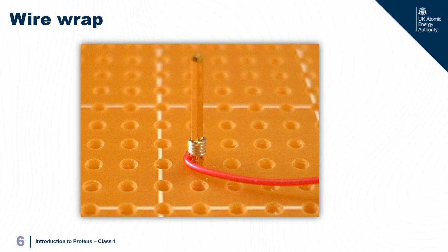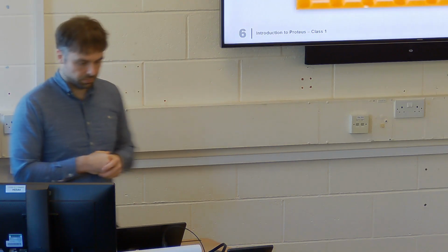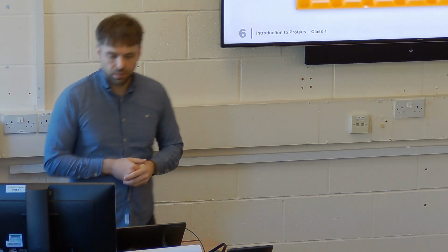So moving on from that, we developed, I think, around the 1950s, got popular in the 1960s, wire wrap. Your components go onto your substrate, like your PCB, like FR4 or fiberglass substrate, and then you use these little pegs to connect to the legs of the components, and then you wire wrap a stripped bit of wire around the pegs. Now, you can semi-automate that task using machines to wrap. The use of it peaked in the 1960s. It's sharply declined now because surface mount technology has basically overtaken this completely.